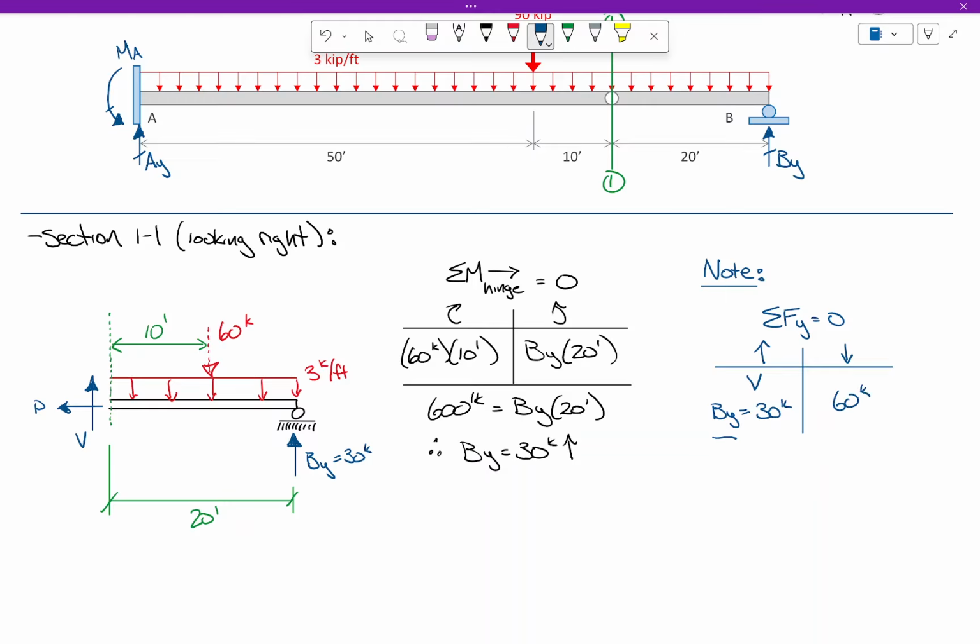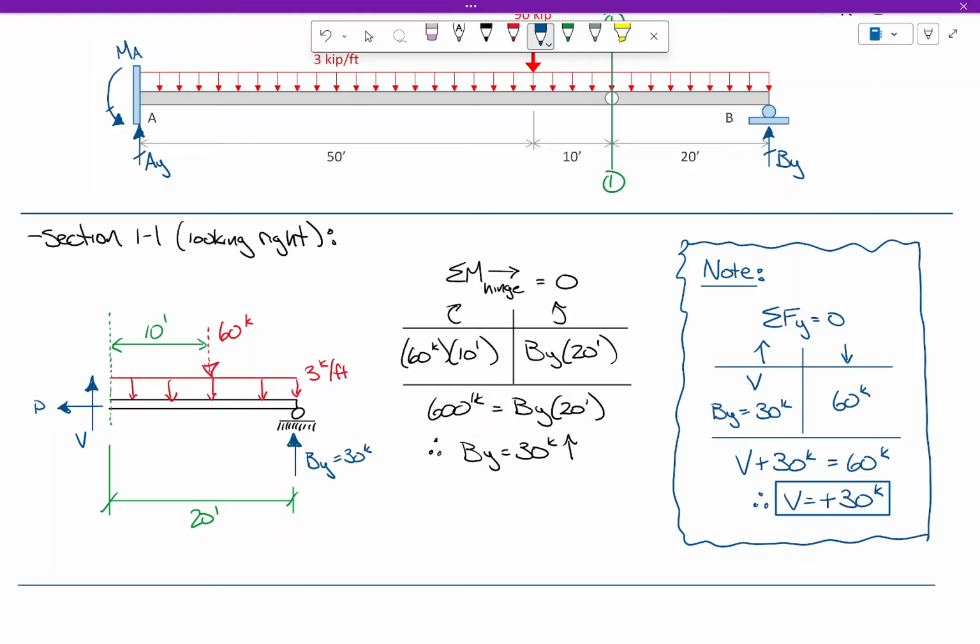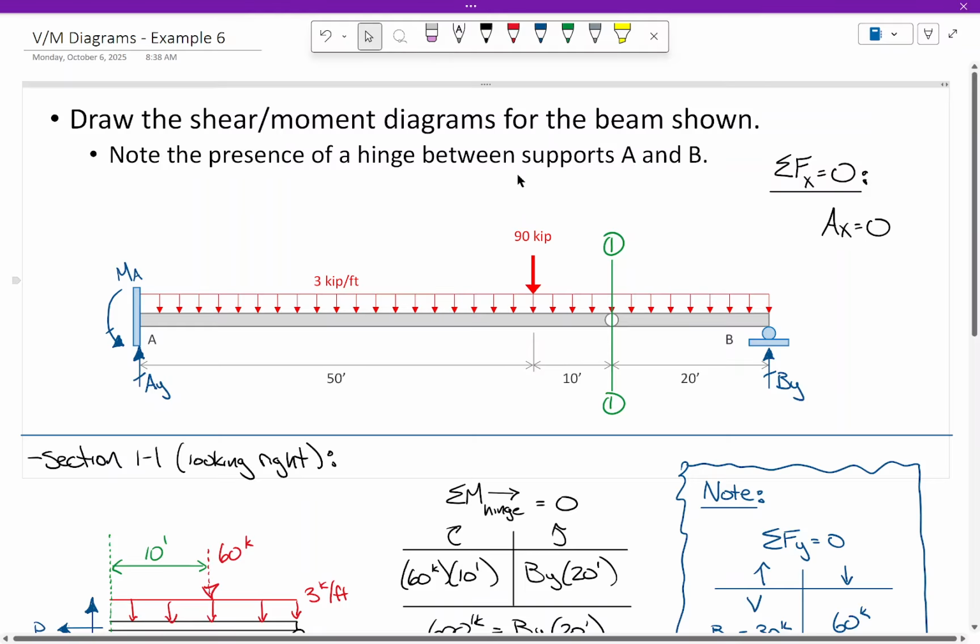Okay. So, tell me what to do now. You tell me, what do I do? Construct the shear. Oh, wait, no. Okay, so let's talk through that. Ultimately we want to construct the shear moment diagram. We can't start that right now, right? Because if we go back to the original structure, we know this reaction, but we don't know these two.